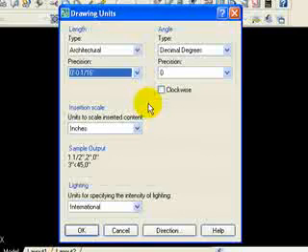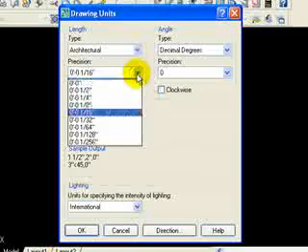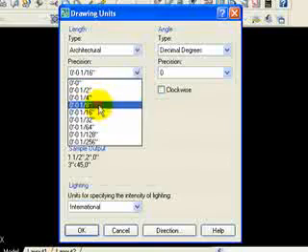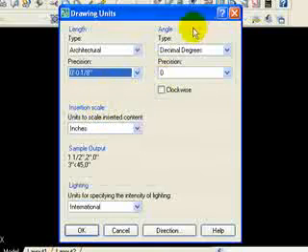It's just that those are the numbers that it's going to be rounding to, like when you list the length of a line. If you want to find the length of a line or the width of a wall, it's going to round that to 1/16 of an inch when it's giving you that information, although it's actually even more precise than that. So you can set your precision to whatever you want. I'll set mine to 1/8, let's say.